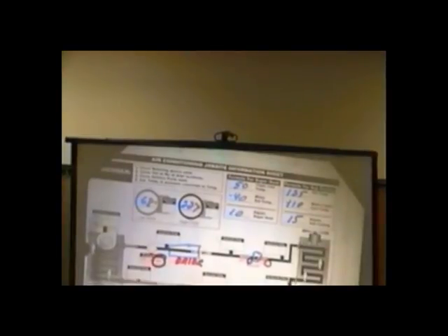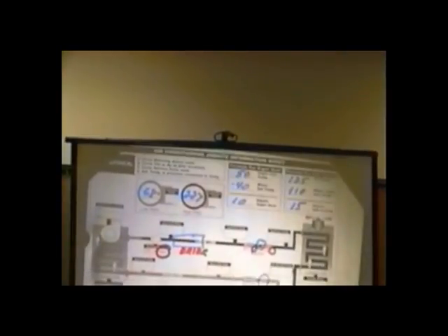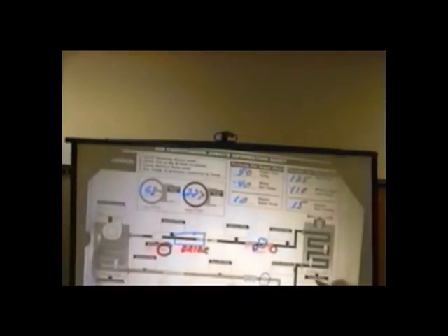Then on the high side, we had a saturation temperature of 125. We had the liquid line temperature of 110, and that equals subcooling of 15 degrees. Oh, I suppose a couple of other things we could fill in here. Outside temperature, we said, was 95. Over here is the vapor line temperature again, it's 50.